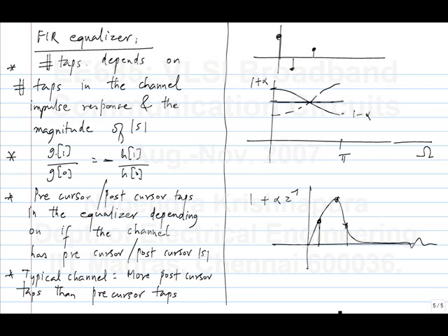Okay, can it be negative? What does it mean if it is negative? This is the response of the channel. Can the first postcursor and precursors be negative? Is it possible, or is it practically not seen, or what is it? What would it mean if the first postcursor ISI is negative?